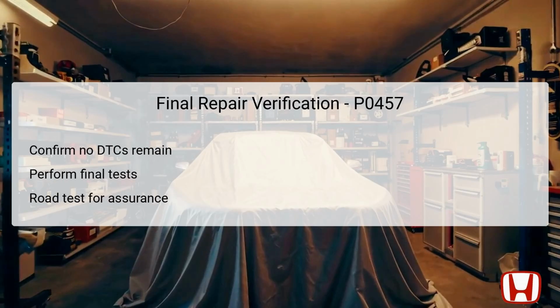Final verification of repairs involves confirming that no diagnostic trouble codes, DTCs, remain post-repair. This ensures that the issues identified in the EVAP system have been fully addressed. After completing the necessary repairs, conduct final tests on the EVAP system again using the HDS to validate that everything is functioning correctly.